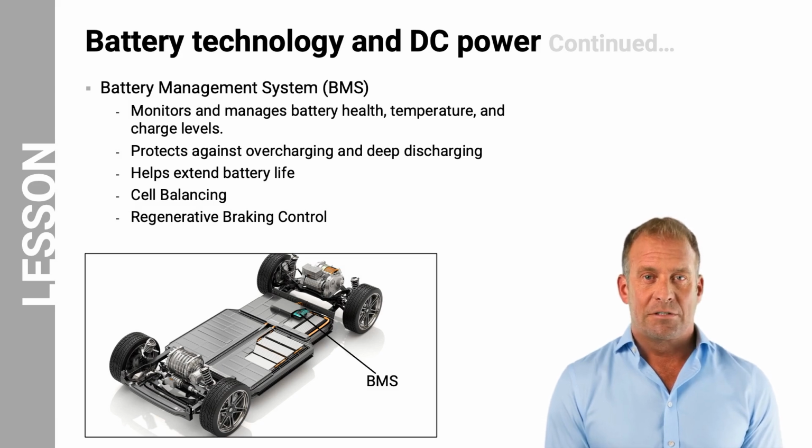A battery management system, abbreviated as BMS, is a critical electronic system in a BEV responsible for managing and controlling the performance and safety of the vehicle's battery pack. The BMS continuously monitors the state of charge of the battery pack, providing real-time information about the remaining energy available for use. This ensures that the driver is aware of the current battery level, enabling informed decisions regarding driving range and charging requirements. By monitoring and controlling the temperature of the battery cells, the BMS prevents overheating during charging or discharging cycles, which can degrade battery life and pose safety risks.